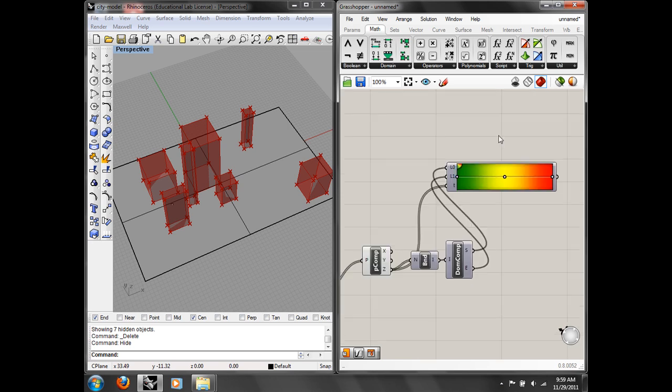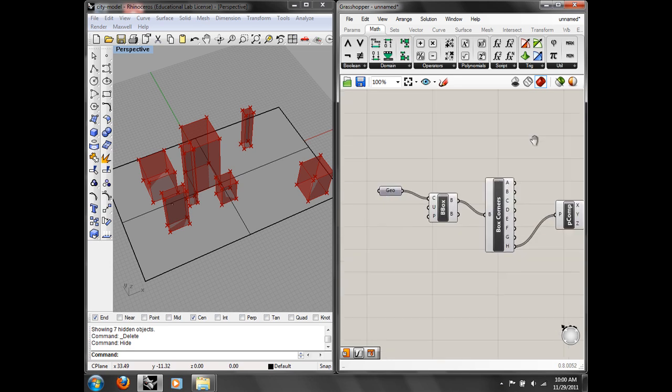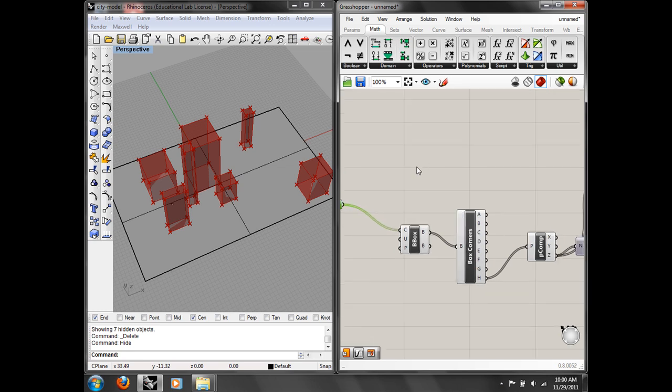Colors only apply to meshes. We haven't really talked about this too much, but in Rhinoceros, if you have used it a lot, pretty much everything starts off as a surface or a poly surface. They're these kind of complex curves. Meshes are kind of dumb polygons, and in order to make anything have a color, you need to convert the surfaces into these dumb polygons. So we need to go back and convert our geometry, which is a surface, into a mesh.